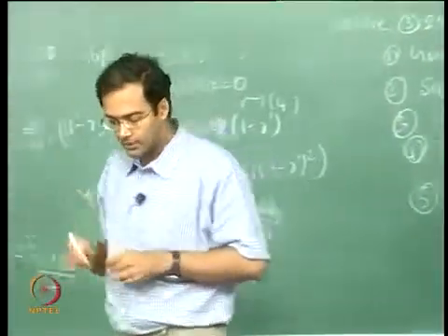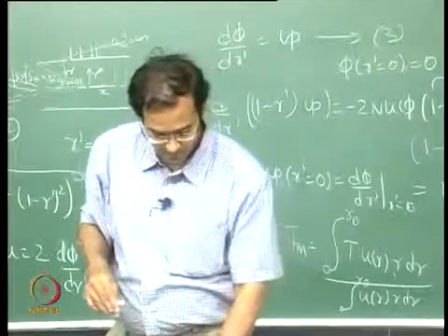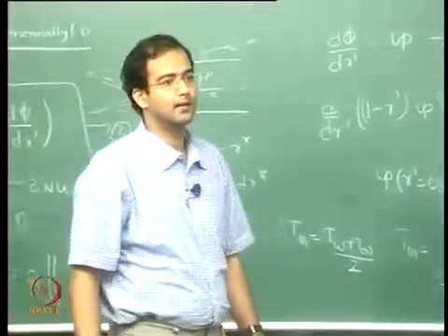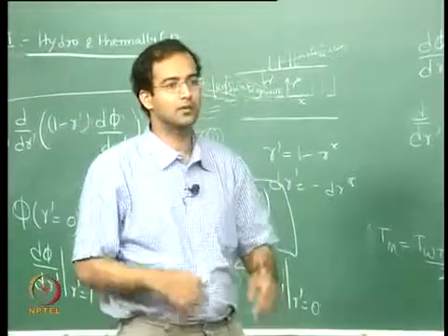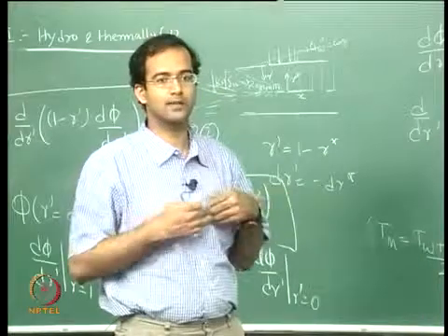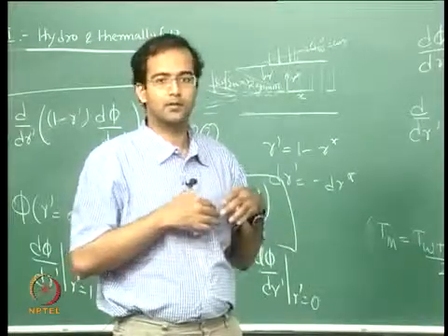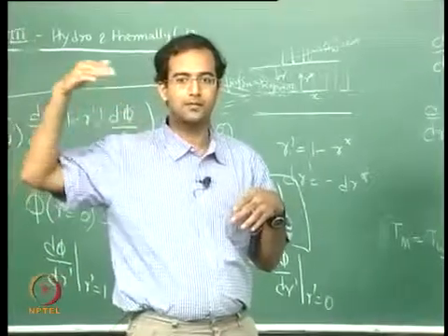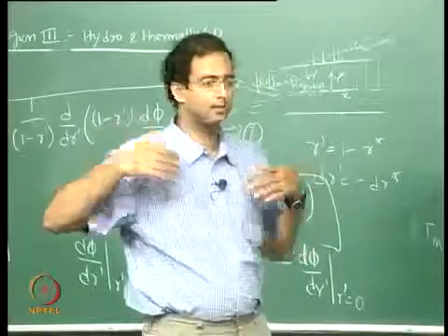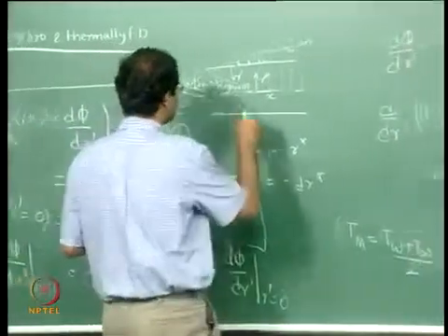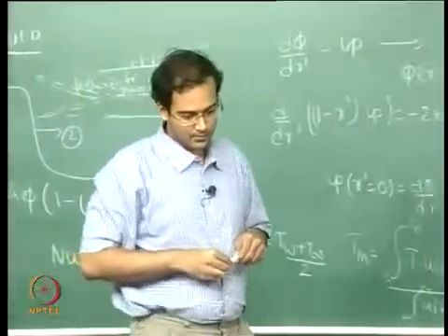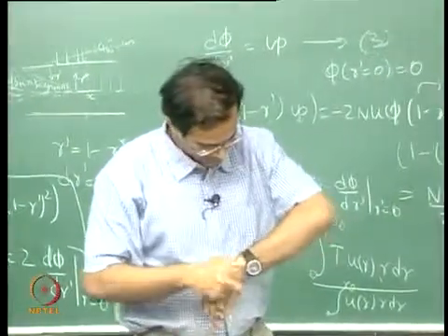there is no concrete reason why this should be higher, but you should all remember that a constant heat flux case will generally result in a higher heat transfer coefficient. This is true even for external boundary layers, you have observed it. In external boundary layers the two boundary layers never merge, the boundary layer keeps on growing, so there the fluctuations will be quite dominantly seen, whereas here the two boundary layers merged and therefore you can only attribute some fluctuations towards the center line, okay. So this is something that you have to pay attention to.